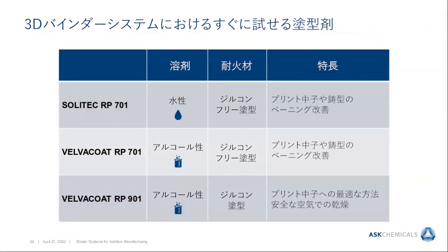Those coatings are specially adjusted to the fine sand used in the 3D printing process, and also in their impregnating characteristics, so that some appearing roughness on the cores, since they are not molded in a tool, there is some inherent roughness to the cores, can be compensated for. So adjusting the particle size as well as the solid content in those special coatings allows us to tailor them for this specific material system, the 3D printing material.